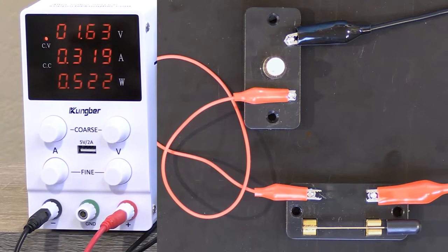Now in the beginning of the lesson, I said it didn't make any sense when someone tells you, hey, there was 5,000 volts flowing in that circuit. Okay, that doesn't make any sense. Because now you know voltage doesn't flow. Voltage is just the pressure, the electrical pressure trying to make a current flow. But the actual current is what the second number is, the amperage or the amps.